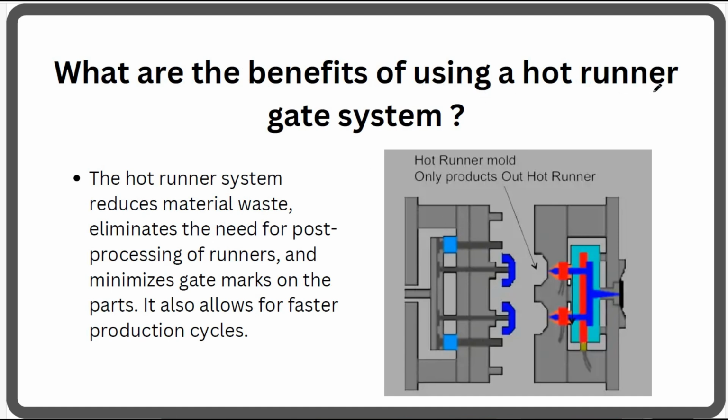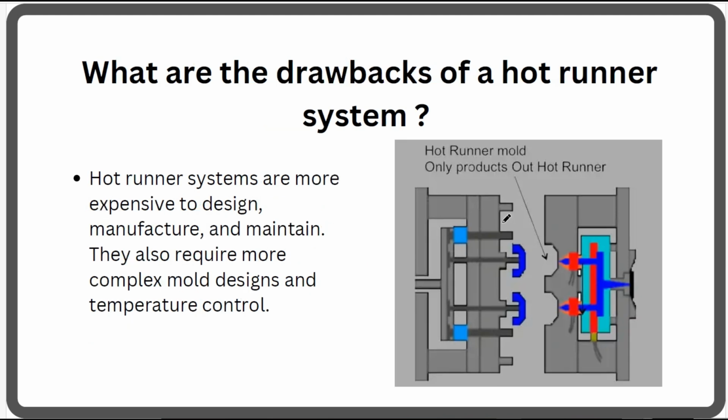So what are the benefits of using the hot runner gate system? As I said, the cycle time will be short and there is no wastage. But this requires careful attention to maintaining the proper temperature, and maintenance is also required.